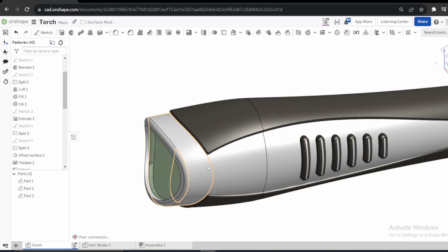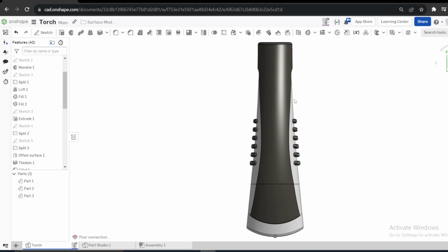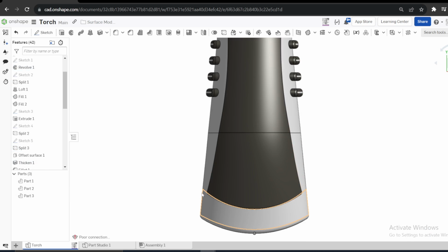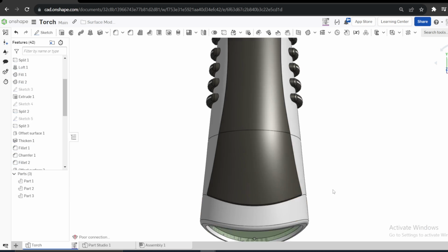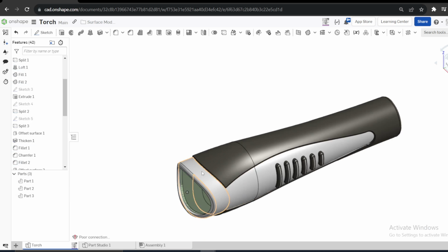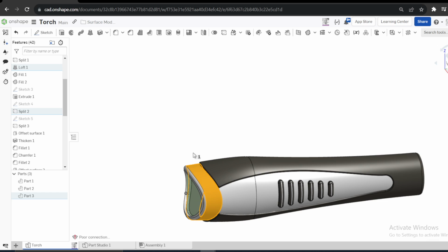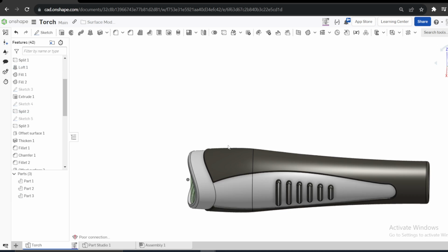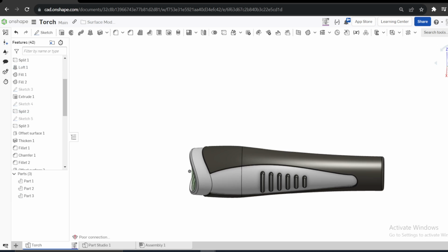Then I'm going to create this sketch here. You can see from top, this is a sketch here. This semicircle arc. Offset it, then split, so that you can have, yeah, this section. You see the section here? Yeah, let's do that now.